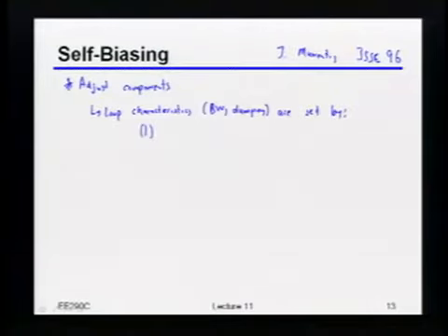One, you want them to be set by whatever your reference frequency is. Okay? So in other words, if I have a certain reference frequency coming in, I always want my loop bandwidth, for example, to be 1/10 of that reference frequency, or 1/5, or 1/20, or whatever the magic number ends up being. Okay? The other thing that it's going to be set by, maybe you guys can guess. What else am I going to have to set it by? How am I going to set things to be 1/10, or 1/20, or 100th, or something like that?